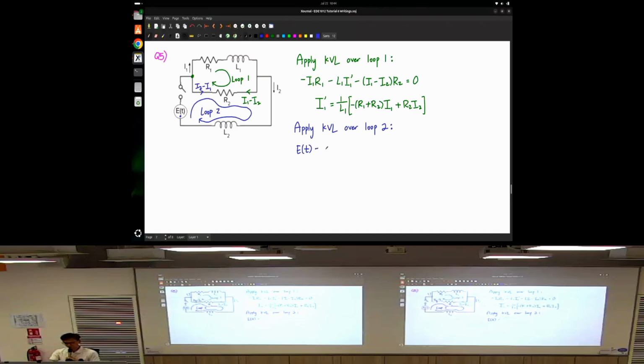So you have a voltage drop of R2 multiplied by I2 minus I1. Okay, it must be consistent. If you show this direction as I1 minus I2, the opposite must be I2 minus I1. Then after that, you are flowing through L2 because this one got nothing. R2 here, then after that here, pass through L2. So minus. Your I2 is passing through L2, so it must be L2 times I2 prime. Then you go back to the battery, so it goes to 0.